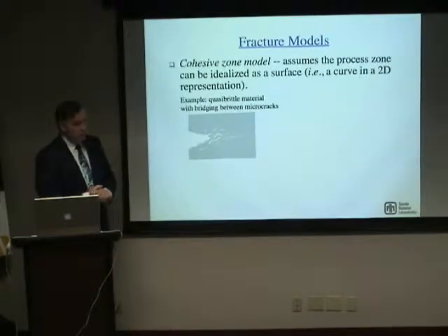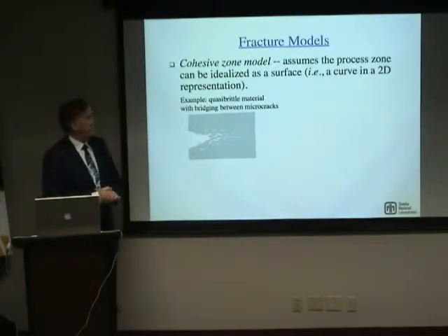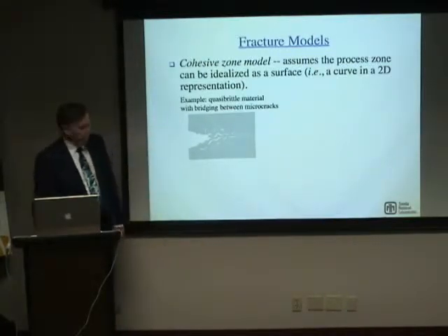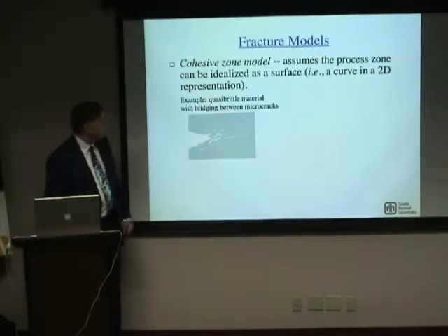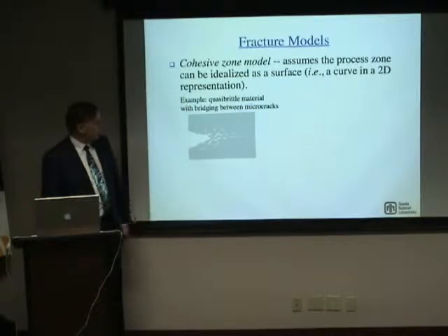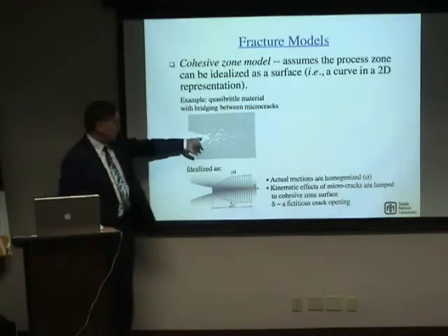Now, numerically, to represent this process zone for a cohesive crack, we'll use the term cohesive zone model. This assumes the process zone can be idealized, as I mentioned earlier, with the cohesive crack assumption. I'm going to show the idealizations incorporated with this assumption by looking at the case of concrete, where you have micro cracks that initiate, grow, and then coalesce.